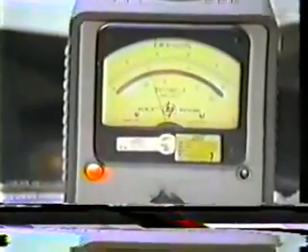And it peaks out at a frequency of almost precisely 2,220 kilocycles. So what we'll do next is plug this into our equations and determine the speed at which our impulses propagate on the coaxial cable.